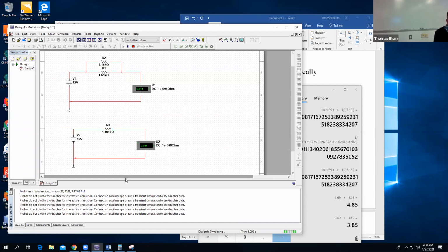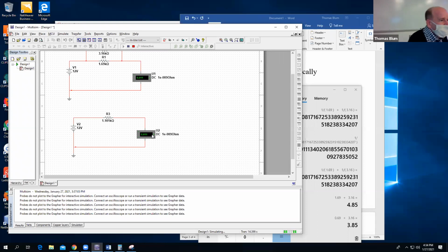Okay. So the two resistors on the top were in parallel. They were connected by wire on one side and wire on the other side. I played my reciprocal addition game, got the equivalent resistance, put in that equivalent resistance, and I have the same effect. For the same voltage of 12 volts, I got the same current. Okay, so that is the game with resistors, series, and parallel.